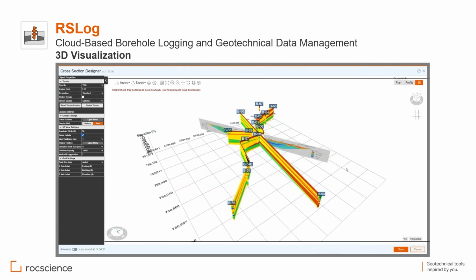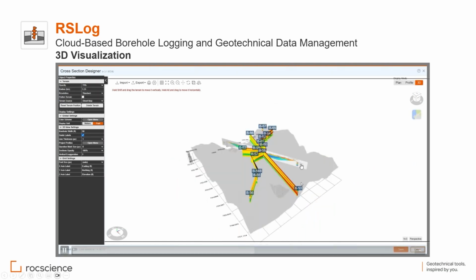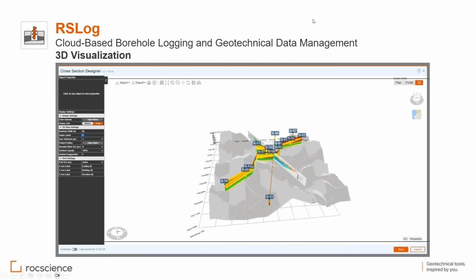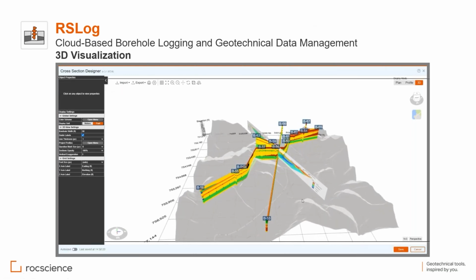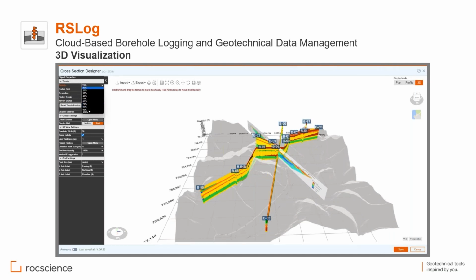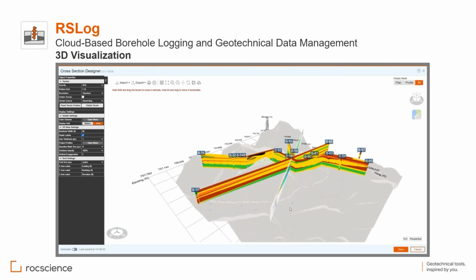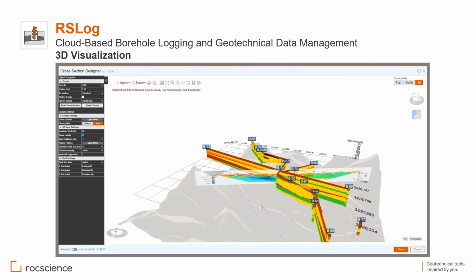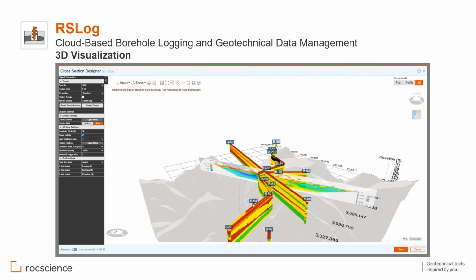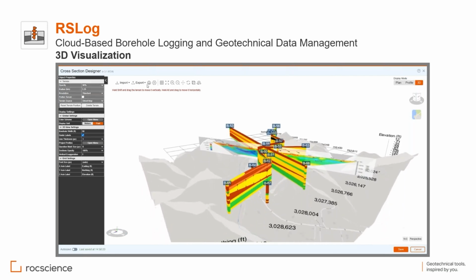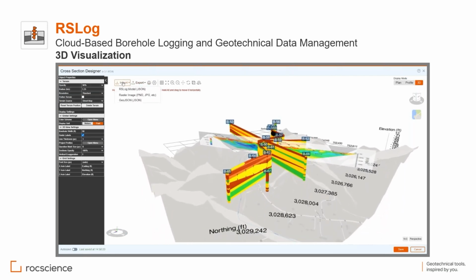Another thing I want to show you here is that in this example, you see geophysical test results. This is electrical resistivity test results in this example, but it gives you the idea. Pretty much any type of test results that you want to add here, any type of geophysical test, the only thing you need to do is export that test result, in this case electrical resistivity, to a PNG file, an image file.